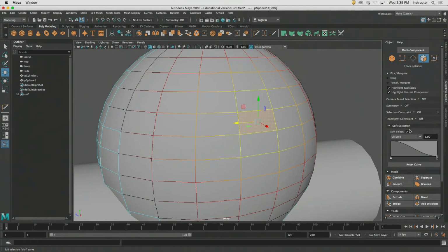They've put the keyboard shortcut in the worst place possible, and that's right down there next to the space bar. And you're going to bump it on accident. It happens all the time. I do it where I bump it on accident and like soft select's on all of a sudden, right? So the B key is what turns it on, okay? Now soft select allows us to select a point, and now we're creating a gradient across our mesh, okay?